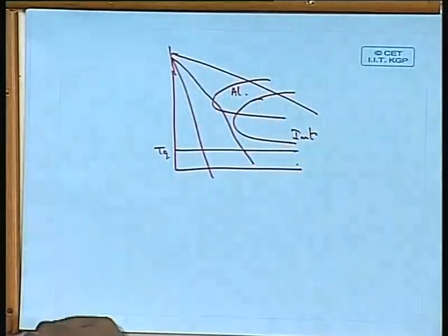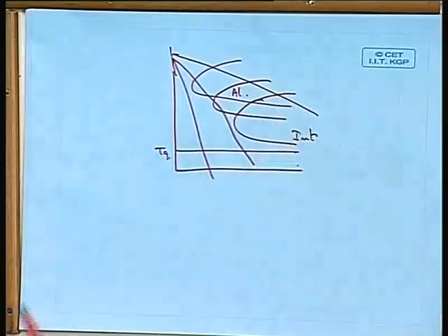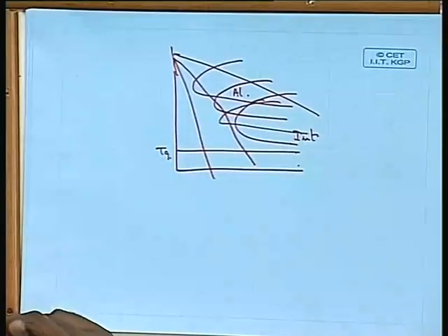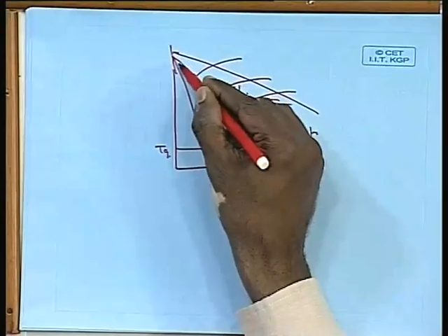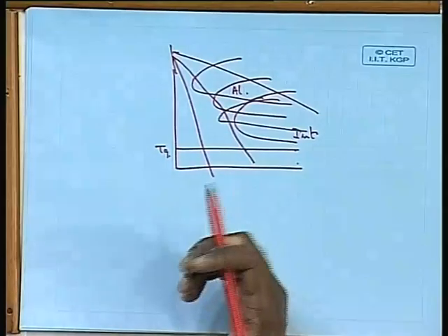And in case you have quasicrystals in a system having Frank-Kasper phases, you will have, let us say, a quasicrystal somewhere here or maybe somewhere here, depending on the type of system, so that you can have a combination of amorphous plus quasicrystal or amorphous plus aluminum plus quasicrystal.